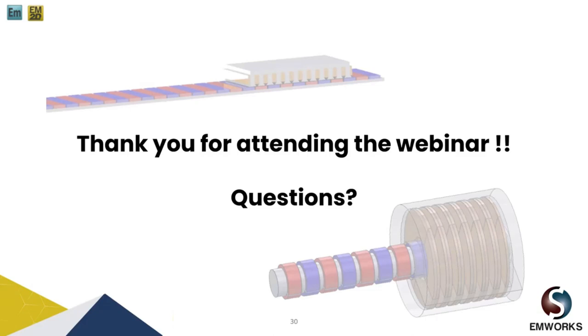Next, how do you determine the gap? I think you mean the air gap between the rotor and stator. From an electromagnetic point of view, you want as small a gap as possible between the stator and rotor, to have better flux flow and lesser reluctance, because air also provides reluctance in your path. For better usage of the magnet flux and good linkage with the conductors placed inside the stator core, the ideal case is to have it as small as possible. But practically, it is very difficult to achieve this tolerance. So generally we go with a 0.05 millimeter air gap in a rotary motor.